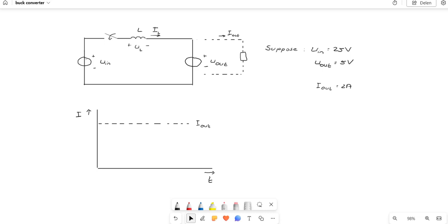Hi everyone. In almost every piece of electronic equipment you find switch mode converters, which convert one DC voltage to another one. For instance, 5 volt to the lower voltages necessary for your processor, like 3.3 volt or even 2.5 or 1.8 volt. In this video I'm going to discuss the easiest one, the basic converter, which is called the buck converter, which converts higher voltages to lower voltages.